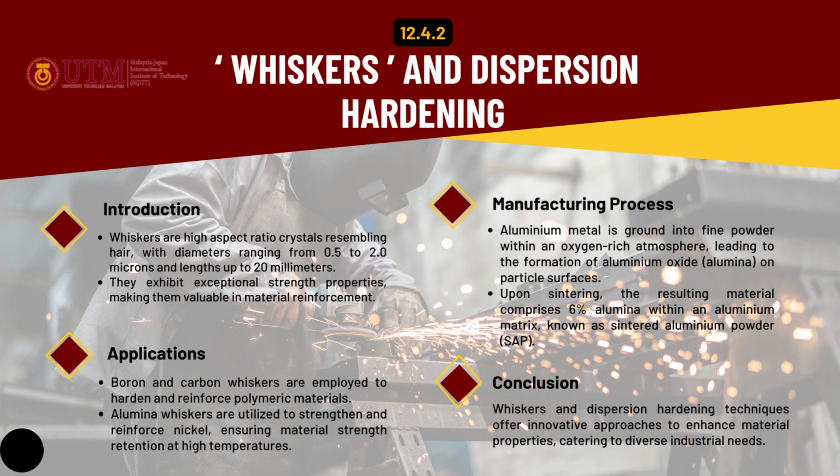For applications, boron and carbon whiskers are employed to harden and reinforce polymeric materials. Alumina whiskers are utilized to strengthen and reinforce nickel, ensuring material strength retention at high temperatures. For conclusion, whiskers and dispersion hardening techniques offer innovative approaches to enhance material properties, catering to diverse industrial needs.